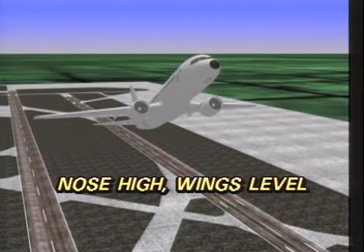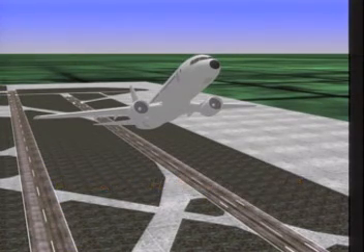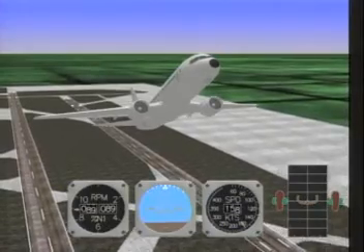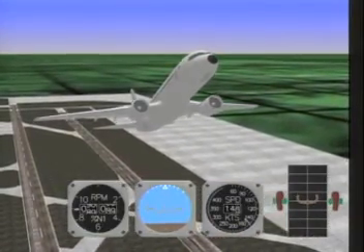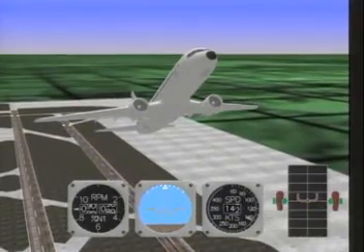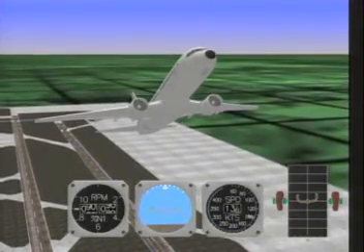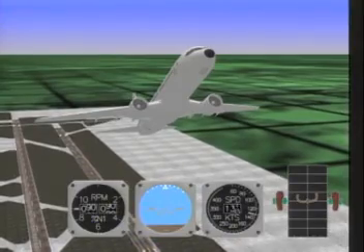Imagine a wings level situation where the airplane pitch attitude is unintentionally more than 25 degrees nose high and increasing. In this case, the airspeed is decreasing rapidly. As the airspeed decreases, the ability to maneuver the airplane also decreases. Recognize and confirm the situation.